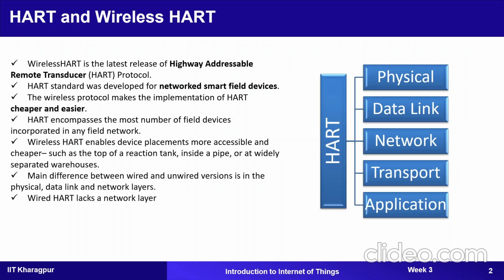The next point is transmission synchronized using 10 millisecond slots. So with the help of these superframe slots, that is the 10 millisecond slots, the synchronization can be provided for the transmissions. During each slot, all the available channels can be utilized by various nodes in the network, allowing for the propagation of 15 packets through the network at a time, which also minimizes the risk of collision. Because in case of HART, 15 channels are used, so at the same time we can send 15 packets.